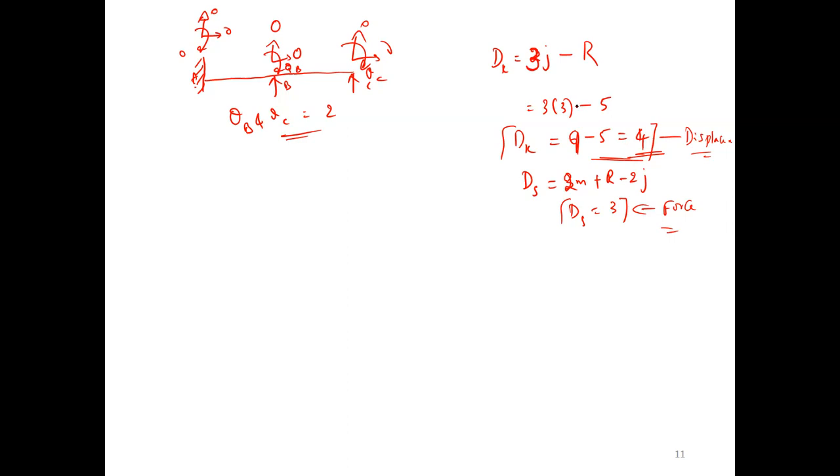See, here we wrote the equation with reference to equilibrium equations as well as external support reactions. But if you observe the displacement, this is degree of freedom. This is called degree of freedom. So there are 2 technical terms. This is called kinematic indeterminacy.